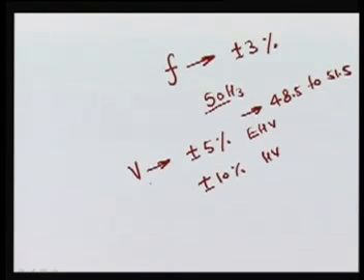In terms of frequency and voltage, these are steady state values. Your frequency is plus minus 3% in the steady state. Similarly, your voltage is also plus minus 5%, or plus minus 10%, in the steady state. But there are many chances that your voltage is different for a fraction of a second. So let us go into more detail about power quality issues.